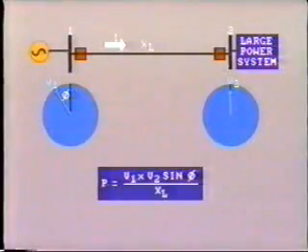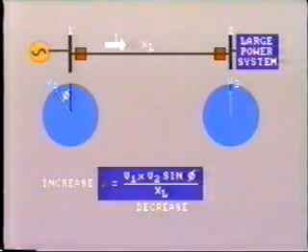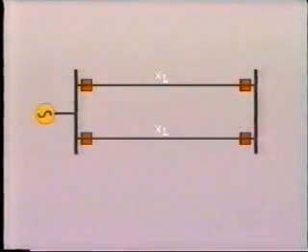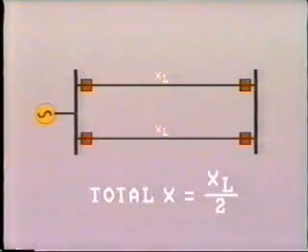Another clear factor is the line inductive reactance. By reducing XL, we can increase the power capability of the line. An obvious example of this is when two lines run in parallel between two buses, so reducing the total impedance by half. This allows us to double the capacity of the circuit.